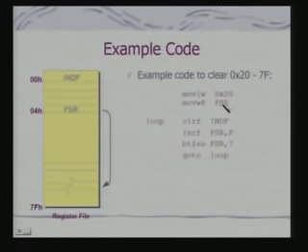And in fact, what you have seen is, interestingly, an application where indirect addressing is really required, because here you are changing the content of a memory location in a loop. So, you cannot use the address directly as part of the instruction, because this address has to be constantly changed. At each step the address has to be incremented, and as we increment the address, we have to go back and clear the content. So, this is a simple usage of indirect addressing and how it is used in PIC.